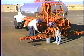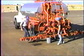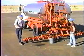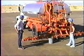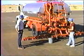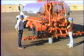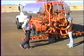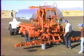And put in a new pin. Just use cotter pins in it. Don't use bolts. Bolts are too hard. They don't shear easy enough, and they wear out the shearing mechanism just because they're too hard. Out in the field, a lot of times you can get by with barbed wire, you can get by with a stick. If you're out of pins, there's some way to get by.